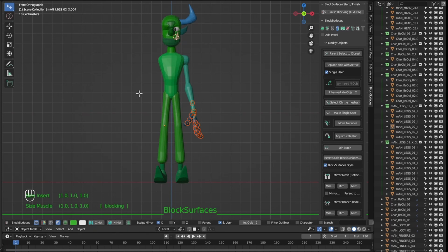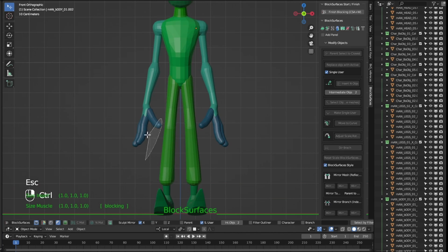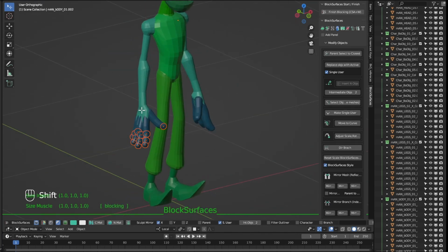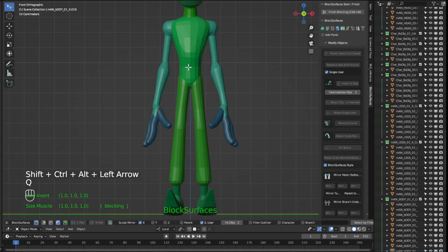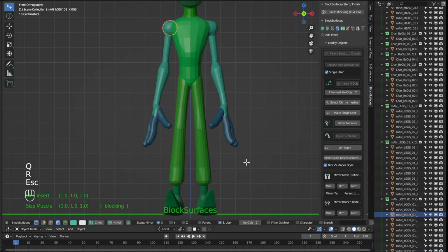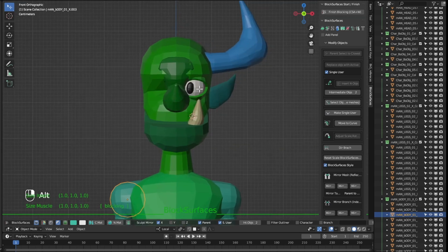If I don't turn this option on, the duplicate objects on the other side will not maintain the hierarchies. I would have to reassign the parent for all fingers of the hand. Again, we would select the objects from the branches, and assign the active object as the parent with the keyboard shortcut. So, with this parental option activated, we would have already had that relationship made on the other side.